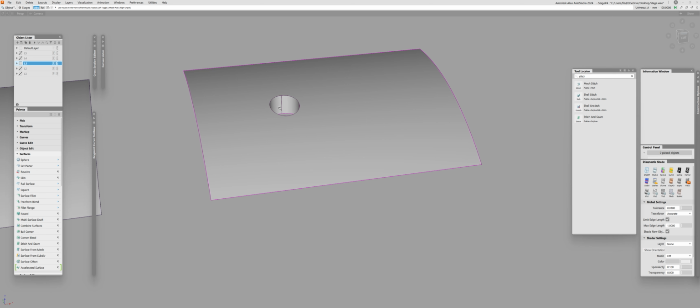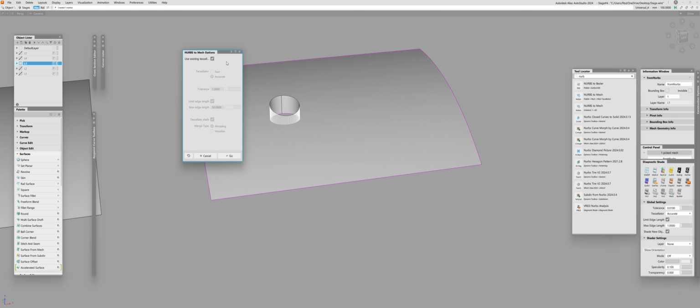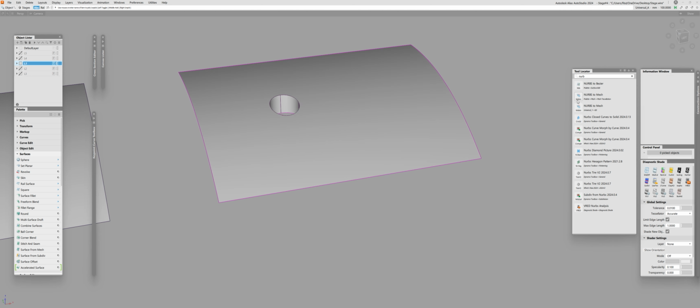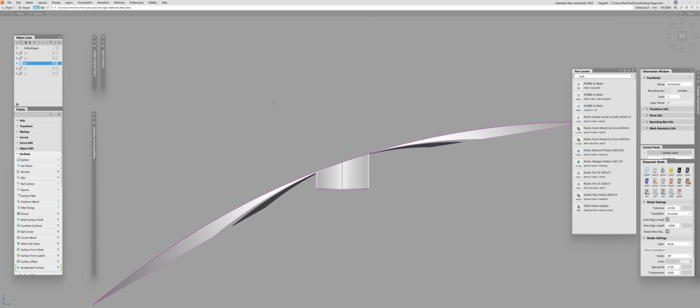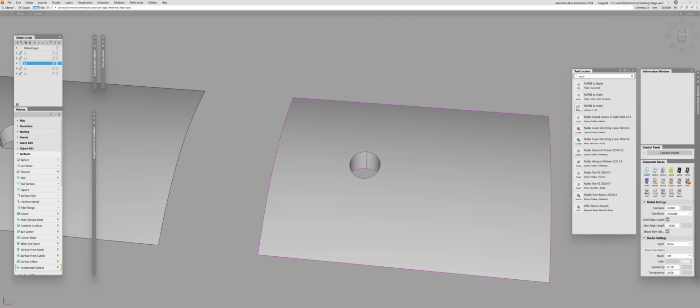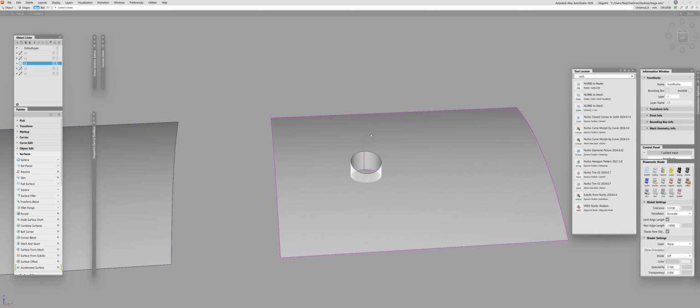Now, what we can do is use the same shell, or basically the binary representation of our surfaces, and then I can convert this, as we did before, to a mesh. Now I just need to delete this because this is too dense. Let's go to the tolerance of, I don't know, that was 0.01, I believe. 0.01, and the limit edge length, let's say it will be 1. Now let me try to do that again. Well, that's still very unmanageable. Okay, let me make a different parameter here. Let's say the edge length will be 10. So just something we can work with.